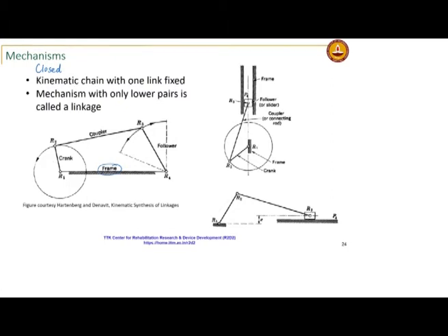The crank and the follower are both pivoting about points fixed to the ground. The coupler is a floating link, and it is the link that connects the crank and the follower. Well, I should not say input link, because sometimes you could have a mechanism that has the coupler as the input link.